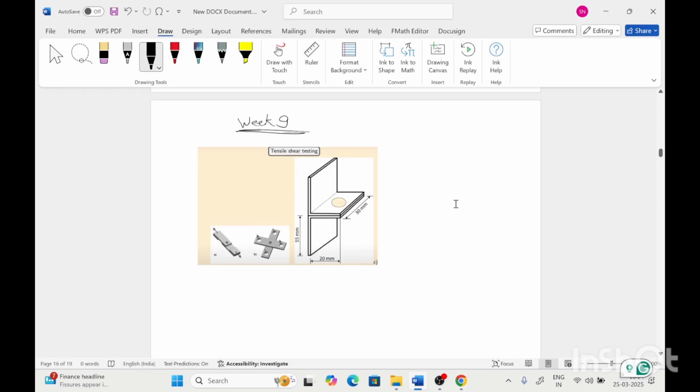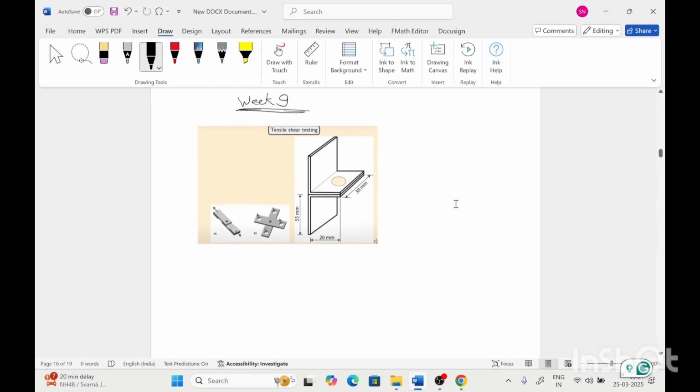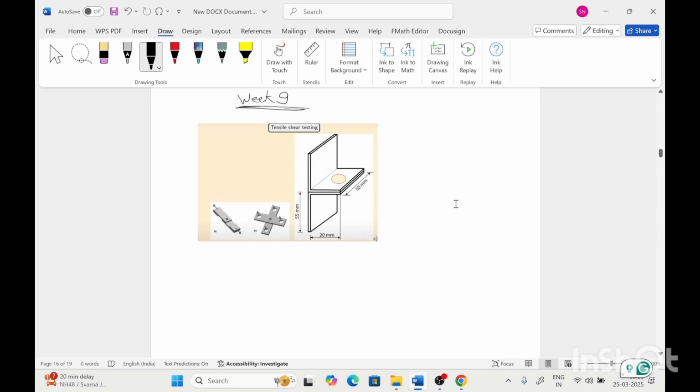Good evening. Today we will further discuss resistance spot welding. In the last week we studied that we can optimize the weld nugget geometry by the weld growth curves. The weld growth curves are generally drawn between current or time versus weld diameter.